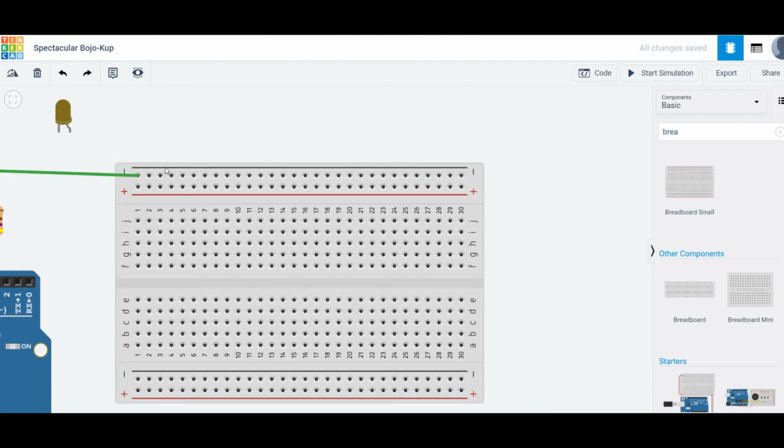Those are connected all to each other. When you hover over one of them, the rest are green, which indicates that those all are connected to each other. So if I connect this one to negative, now all of those already have negative. And those are connected to each other as vertical lines, and those as well.